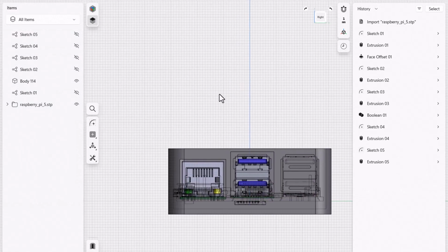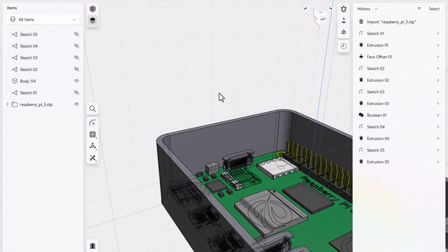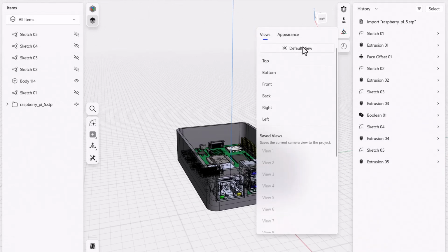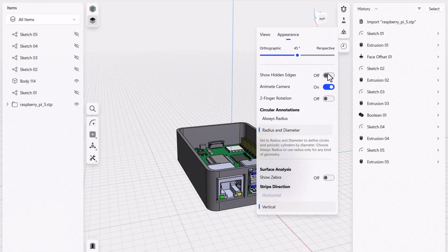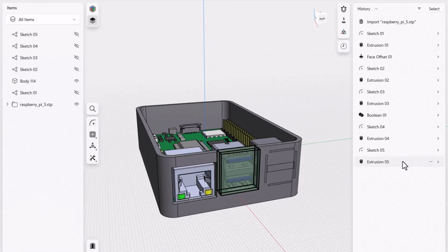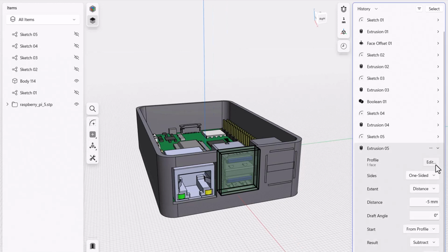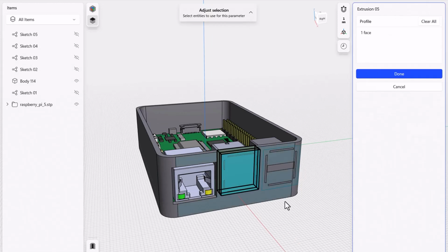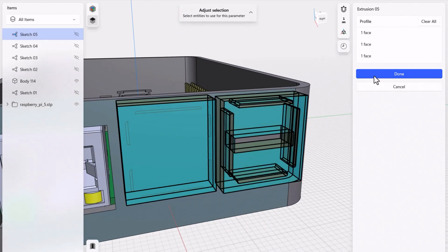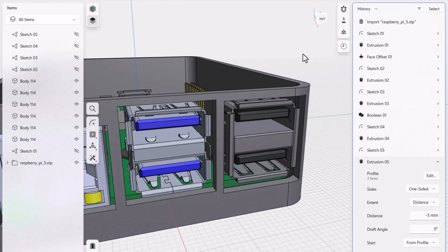And then once you've finished making those edits to the shape, notice over here, if you zoom in, zoom out, let's go ahead and hide the edges. Right now, notice it didn't show up. You're saying, hey, why didn't that show up? Well, over here, you have to go back to that extrusion in your profile. You have to go select this. So here it is. You just have to make sure you select it. Make sure you got those edges there, and then bam, there you go.